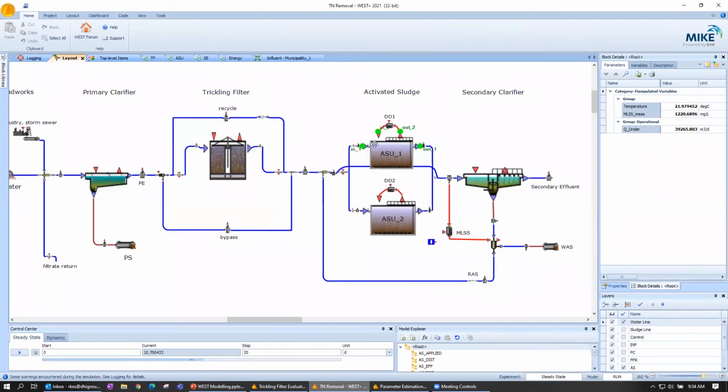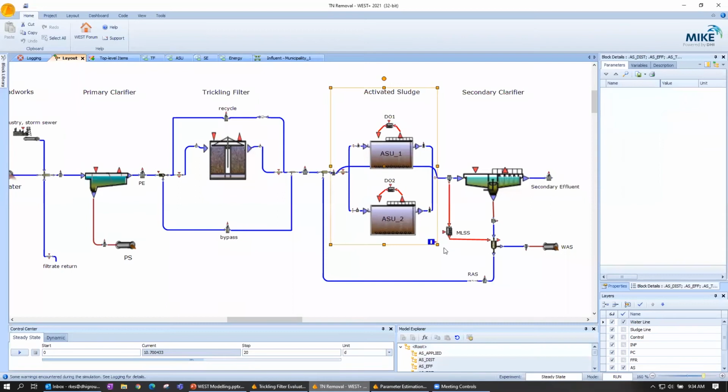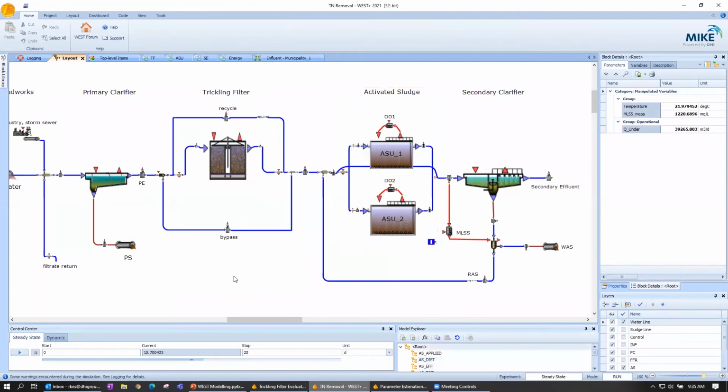But another conclusion that we can draw, besides the fact that we don't have enough volume here for full denitrification or enough carbon, so that was the first conclusion, is that we're going to need more volume, and we recommended, in this case, I think a side stream Anammox, possibly side stream intensification process instead. The Anammox will significantly reduce the amount of carbon that's needed for the denitrification in these tanks, and it also has a nice benefit for aeration rate.